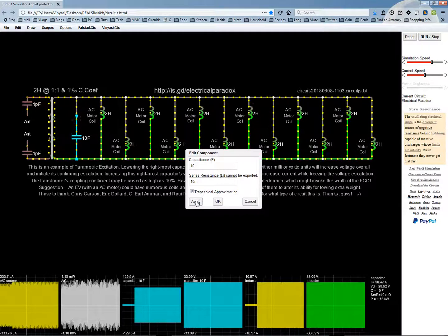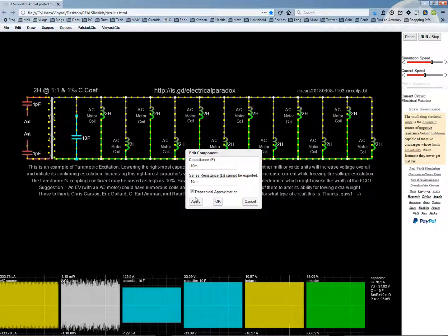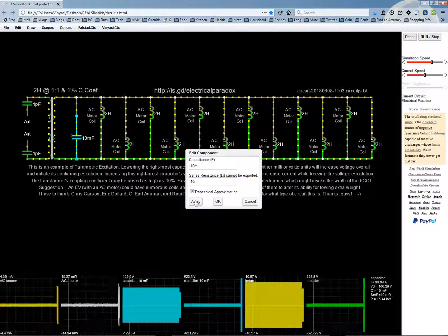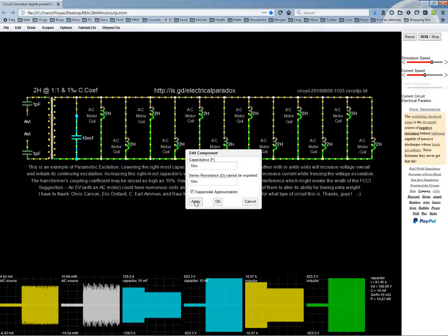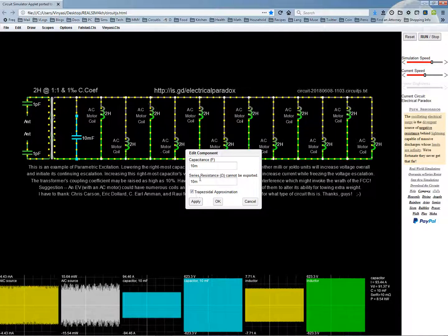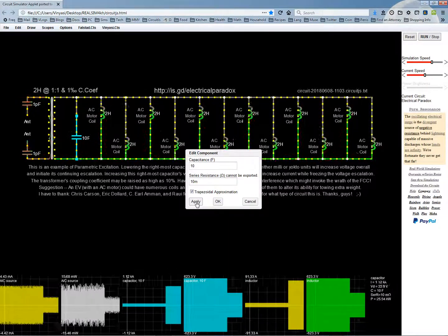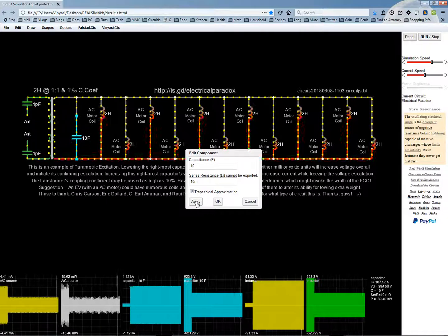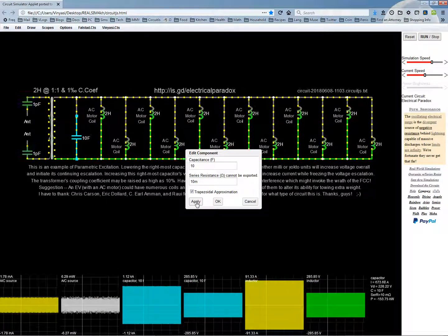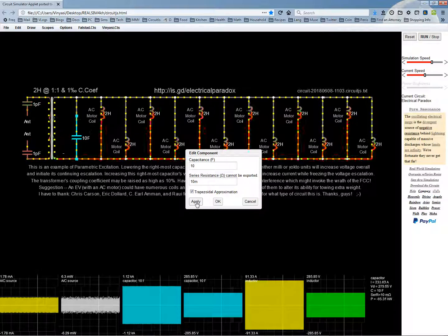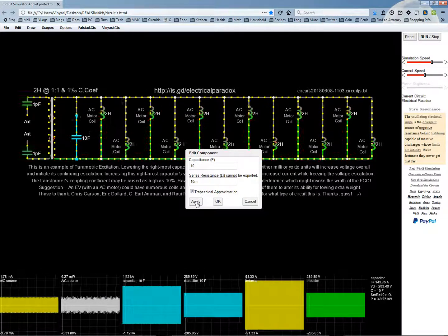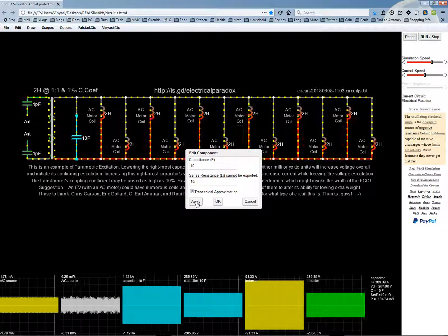So we're up to 10 amps and 33 volts on the coil, or coils. They're all the same, so I only scope one. Oh wow, that's a lot of volts, but that'll come down. So the system has to accommodate high voltage, because of higher voltage and higher amperage than whatever target you're shooting for. So now I've got 90 amps, which means I'm going to have a lot of volts. 285. Yeah, that is a lot. Normally for accelerating a car, you might run it at 200 amps, and cruising might be 50. So this is a little excessive for cruising, like slightly speeding up in traffic.